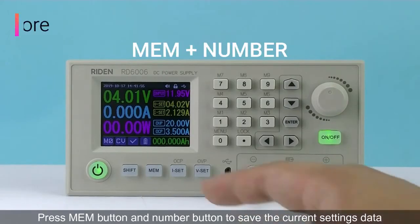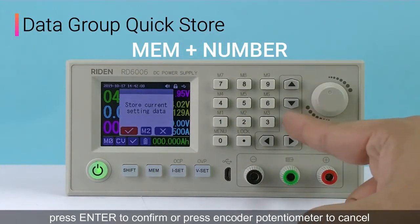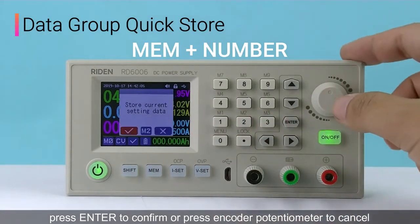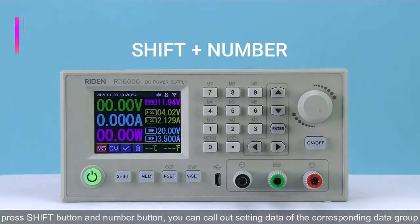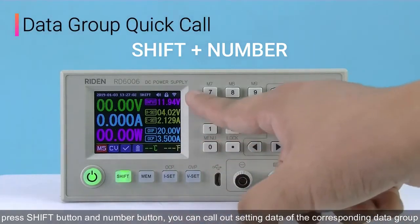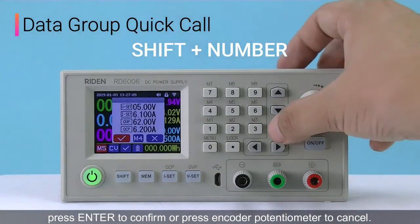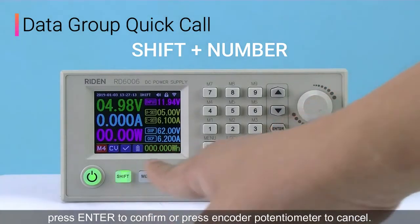Press memory button and number button to save the current setting data to the data group. Press Enter to confirm or press encoder potentiometer to cancel. Press Shift button and the number button, and you can call out the setting data of the corresponding data group. Press Enter to confirm or press encoder potentiometer to cancel.